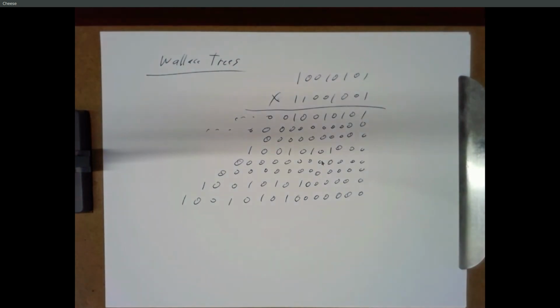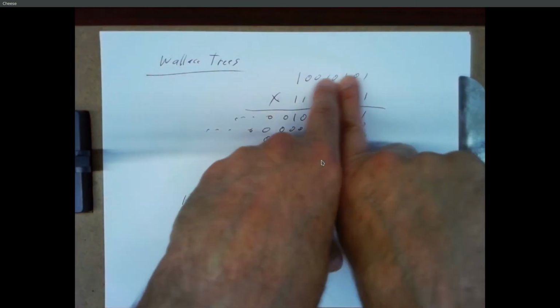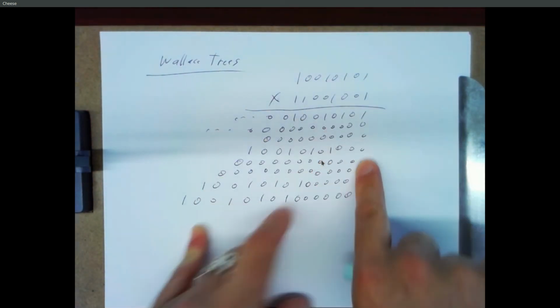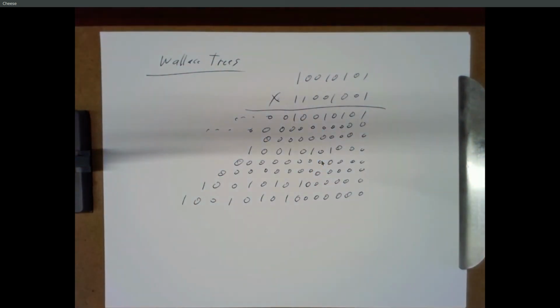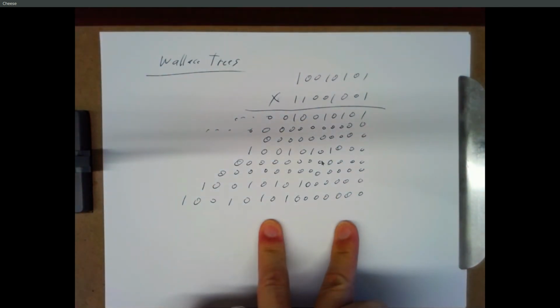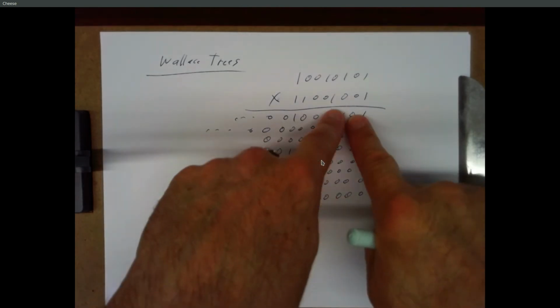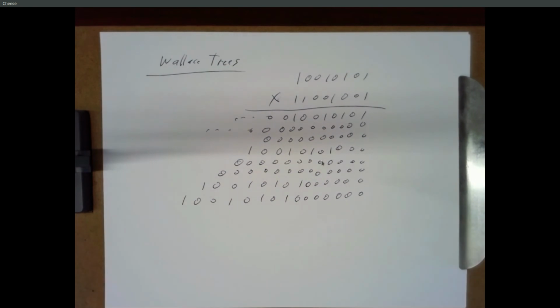So we're trying to multiply two big integers. Coming up with these numbers is just a multiplexer, or maybe it's just an AND gate, right? Just take this bit, AND it with each of these, and you get either the number or you get a 0. The whole trick to multiplication is you've got all these numbers now that you have to add together. And that's a lot of work, right? So if we use our carry save adder, we end up actually doing less work than just going through these and adding them up together.